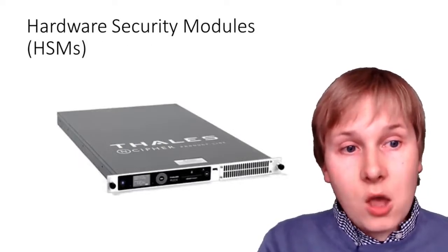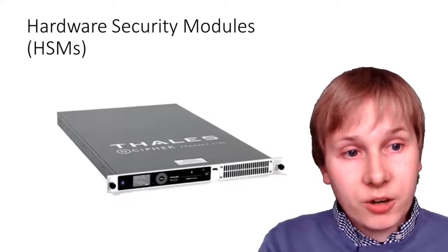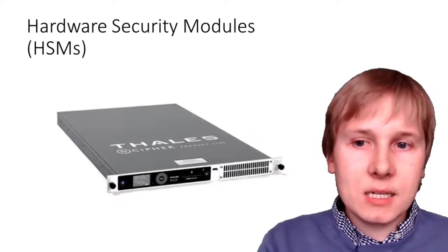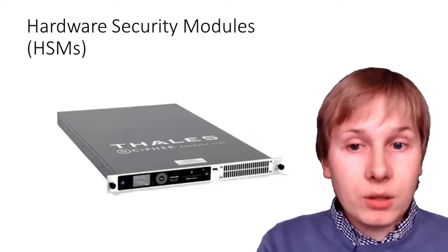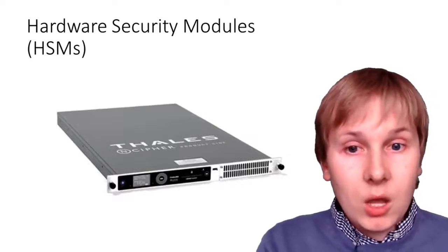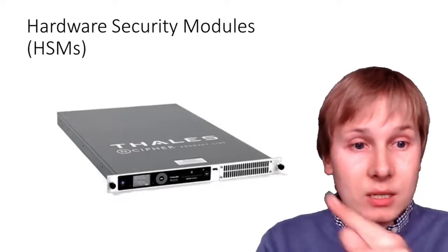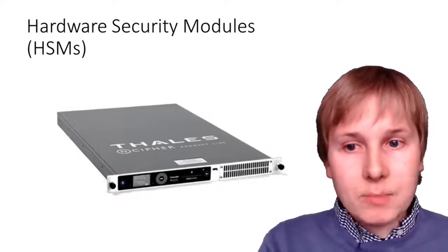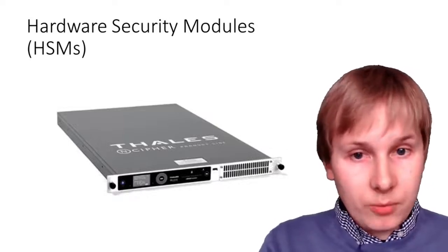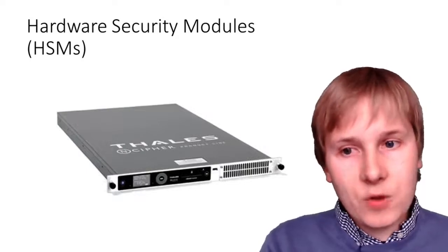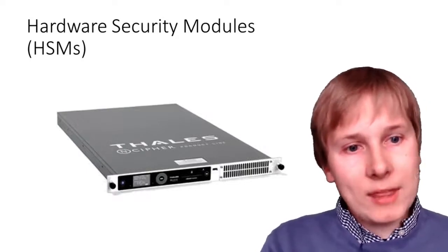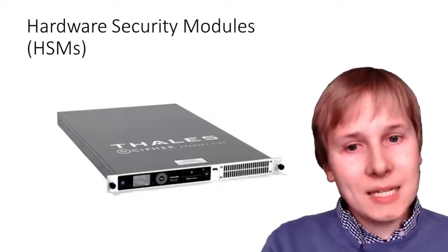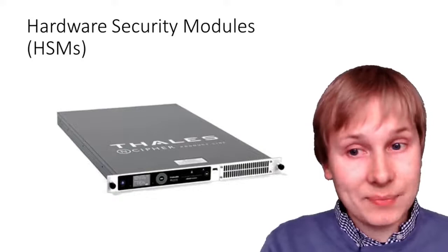A lot of the early work came from hardware security modules in banks. Rather than locking down the entire operating system of a machine, the secret parts go into a standalone cryptographic module, which is its own separate small computer that interfaces with the rest of the machine. These have a robust metal enclosure and contain equipment to perform encryption. The tamper-proofing is designed such that the RAM where the key is stored is zeroed whenever the object is opened, so a maintenance engineer replacing a battery can't get the keys.